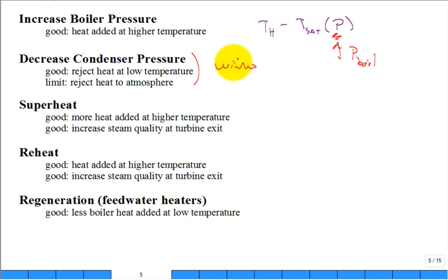And so it's kind of dictated by where you're cooling it. Or if your power plant's located in Alaska year-round, it's cooler than year-round in Corpus or San Antonio or Houston. So your high temperature could be the same, but the low temperature could be different because you're able to get cooler lake water to reject it to. Or even they reject it to not just lake water, river water, ocean water, atmospheric air. There's a number of schemes, depending what you have available.